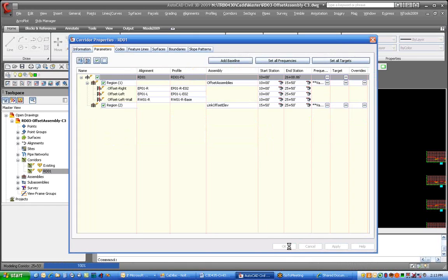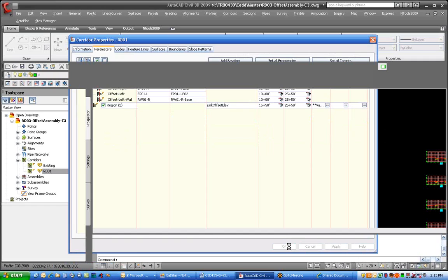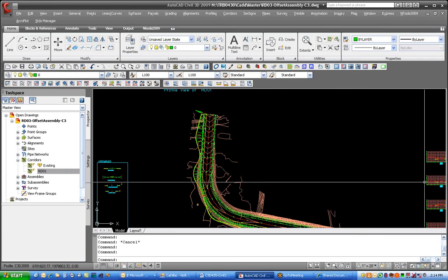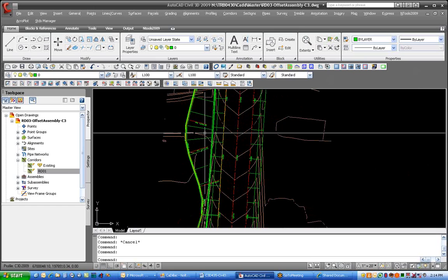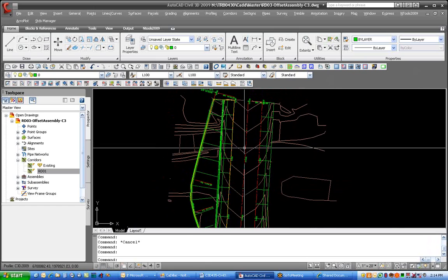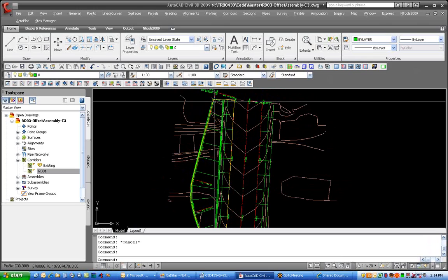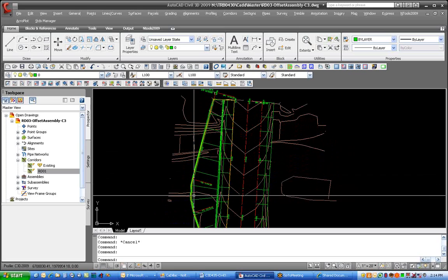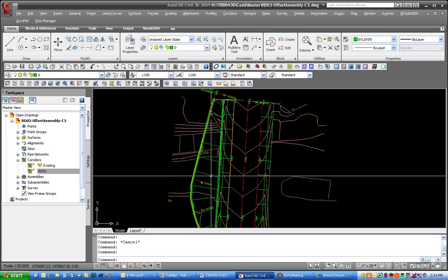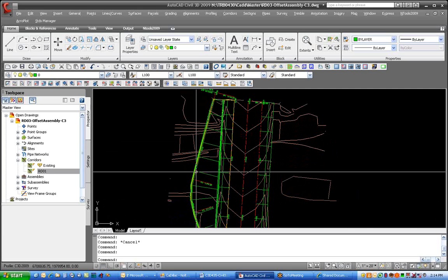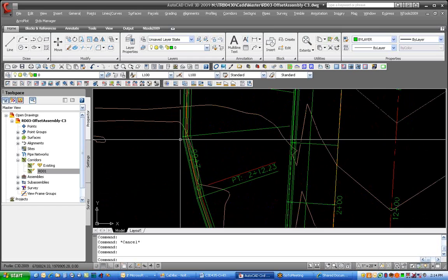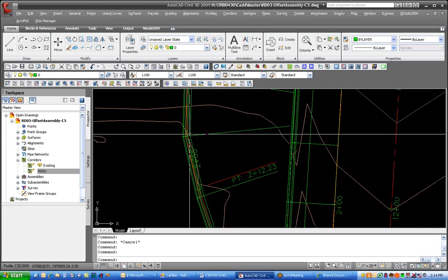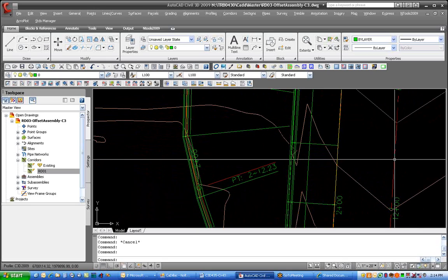I'm going to pick OK here because it wants to rebuild my model. It's out of sync. All right. So what that did for us now, so let's look at this in plan view, and what you'll see by having those separate offsets as my retaining wall goes out around this way, you'll notice now that the sample line, this link line is actually coming off the wall, so you can see how they are actually being drawn perpendicular to the retaining wall alignment, not to the center line.